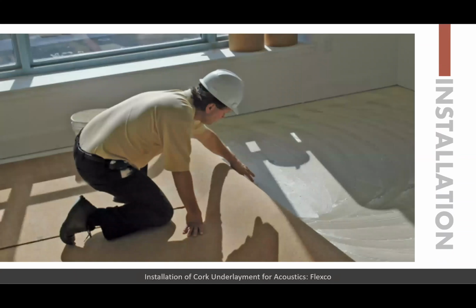There are two main types of installation processes for cork flooring. The more traditional installation method, usually used for cork flooring in tile form, is adhesive connection. First, the flooring tiles need to be acclimated to the environment inside the installation room, similar to what we saw for other types of products in resilient flooring as well. Then the subfloor, such as concrete or plywood, must be prepped to assure that it's even, clean, and free of moisture. As you've seen and heard numerous times.